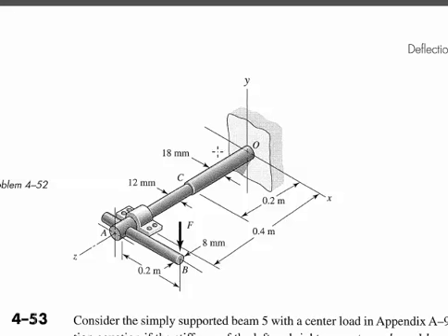We're going to get torsion in this rod. Now this rod has 2 different sizes, which means we're going to get 2 different torsional pieces because the GJ term is different in each region. Then we're also going to get a bending downward of this bar. We have to add those 3 energy type terms together to come up with the total deflection of this beam. And so we'll just try to remember that each of these bars is 0.2 long, and even this one is 0.2 long. So 0.2 will show up prominently, and we'll have 2 torsional terms and 1 bending term.